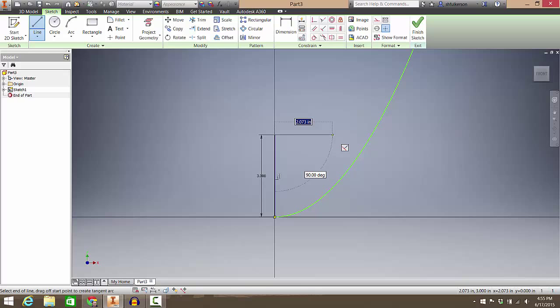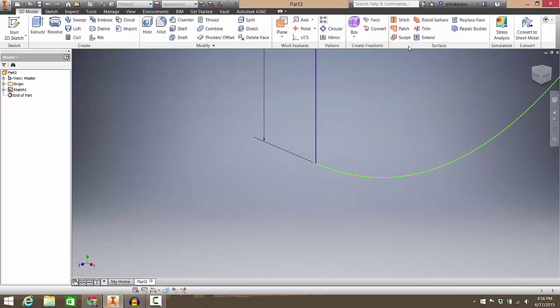But you'll find if you do that, these equation lines aren't actually fixed, which I think is a design flaw, but what do I know? So you're going to go out a straight 90 degrees from there and come and make contact with your parabola. Then it's perfect. Okay, so there is your parabola. There is your sector that we're going to revolve around the y-axis. So we're going to finish that sketch.